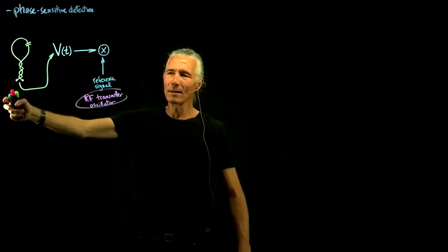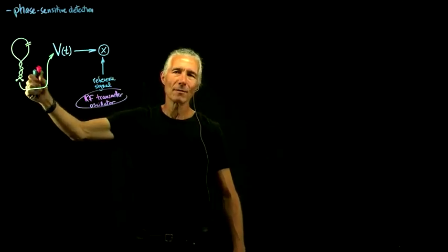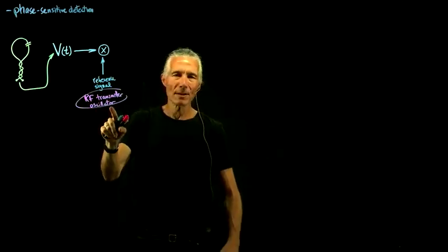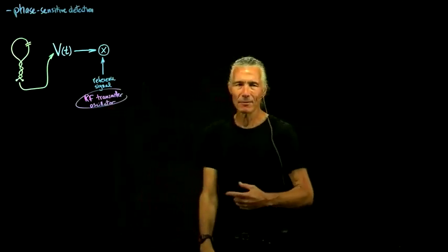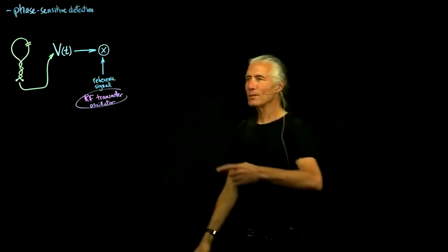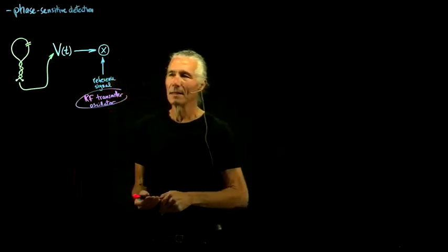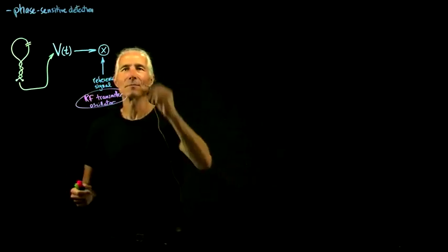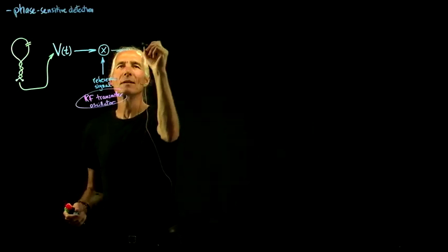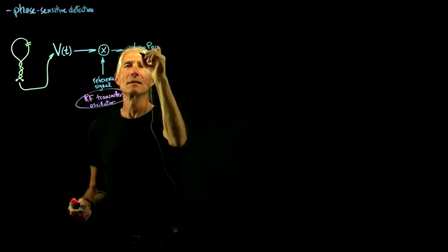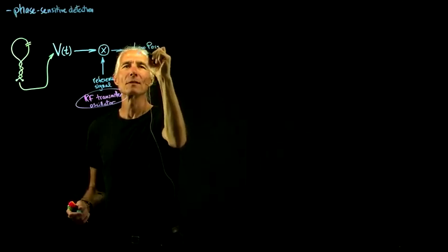So the transmitter would have done something in order to generate a signal in the brain, and then the signal is coming back out, but the transmitter oscillator is still running. And we take that transmitter oscillator signal and multiply it by the signal that we get back from the coil. And then we send it to a low-pass filter. What's a low-pass filter?